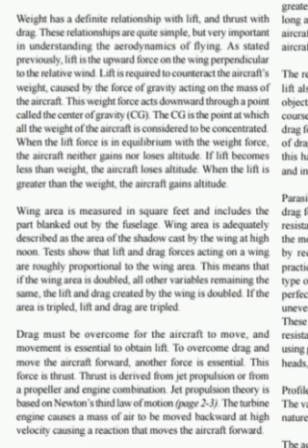The CG is the point at which all the weight of the aircraft is considered to be concentrated. When the lift force is in equilibrium with the weight force, the aircraft neither gains nor loses altitude. If lift becomes less than weight, the aircraft loses altitude.